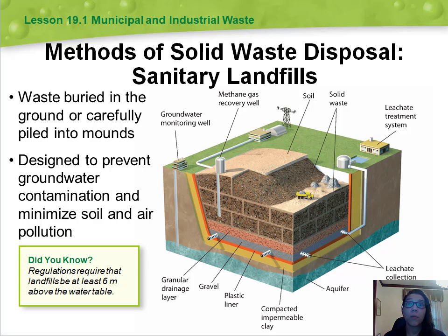Sanitary landfills must also have systems of pipes installed and collection ponds. They also have treatment facilities to collect and treat the leachate. The leachate is a liquid that results when substances from the trash dissolve in water as rainwater percolates or trickles downward.